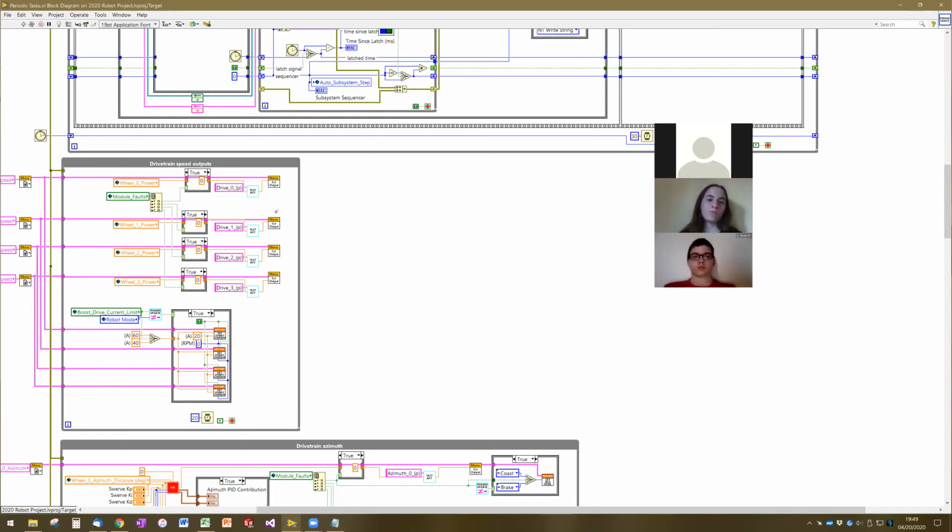We are not doing either of those two methods, so we're still using the most simple method for controlling the wheel speed on the Swerve drive right now, which is direct power application. So right now the code's pretty simple for that, but as we look in the future for improving the reliability and the controllability of the Swerve drive, we can talk about some more advanced speed control algorithms.